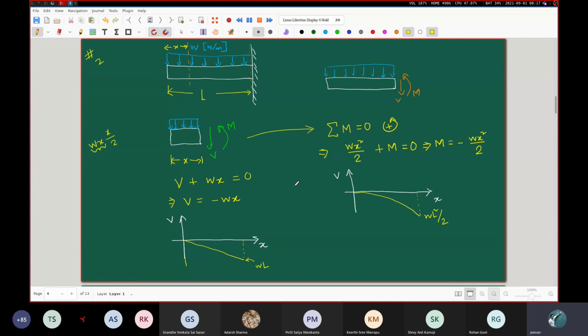That will become even clearer when we go on to the discussion in our next week, when we discuss the various kinds of flexural stresses. You will see why that is important. You have to not only be concerned with the expressions or the values of the bending stresses, but you will have to find out the maximum possible value of the bending stresses. And since the bending stresses will involve in their expression this m, you will have to find out where in the beam the largest value of the bending moment is, correspondingly where the largest value of the bending stresses is, which will actually help you to design the beam. So we'll go into those kinds of discussion, but I just wanted to motivate it.